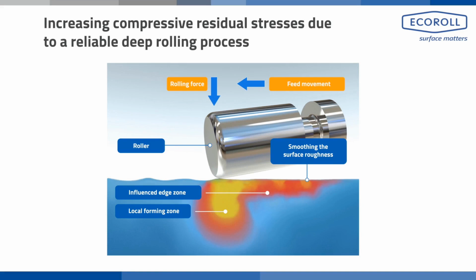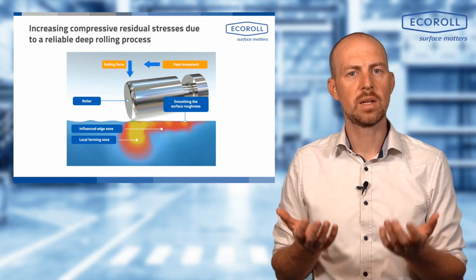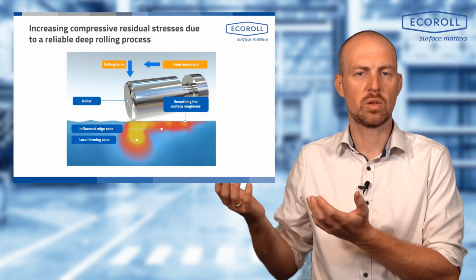These compressive residual stresses have a crack-inhibiting effect. This means that cracks are prevented from forming and spreading because they are compressed by the internal stresses within the structure. This means that crack growth progresses more slowly, and my component will simply last longer under the load.